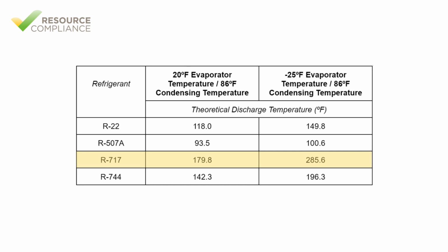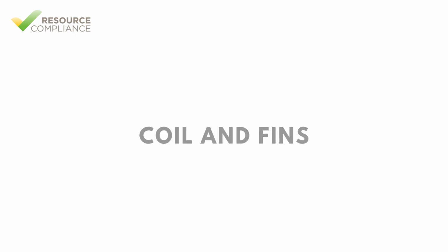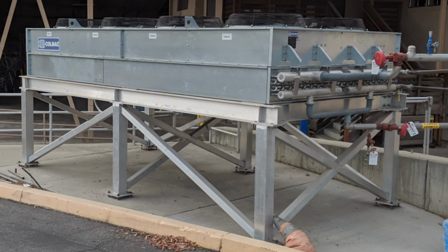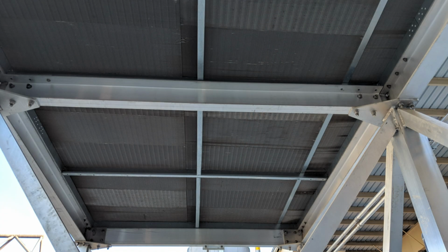The primary components in an air-cooled condenser are: each condenser will have at least one inlet connection to receive superheated vapor and one outlet connection where liquid exits the condenser. The refrigerant flows through a series of heat exchange coils made of copper in halocarbon systems or various steels for ammonia systems. Thin metal fins are attached to the coils to maximize the surface area in contact with the air, enhancing the heat transfer process. These coils and fins provide the necessary surface area for effective heat transfer.